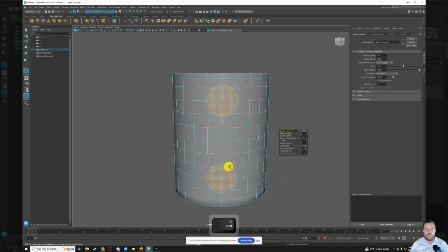All right, now we have 2 rounder sets of quads, but they're a little off center. So we're going to twist them using the twist option here. I found that about 2.2 on the twist, with this size cup, gives you a pretty straight selection.